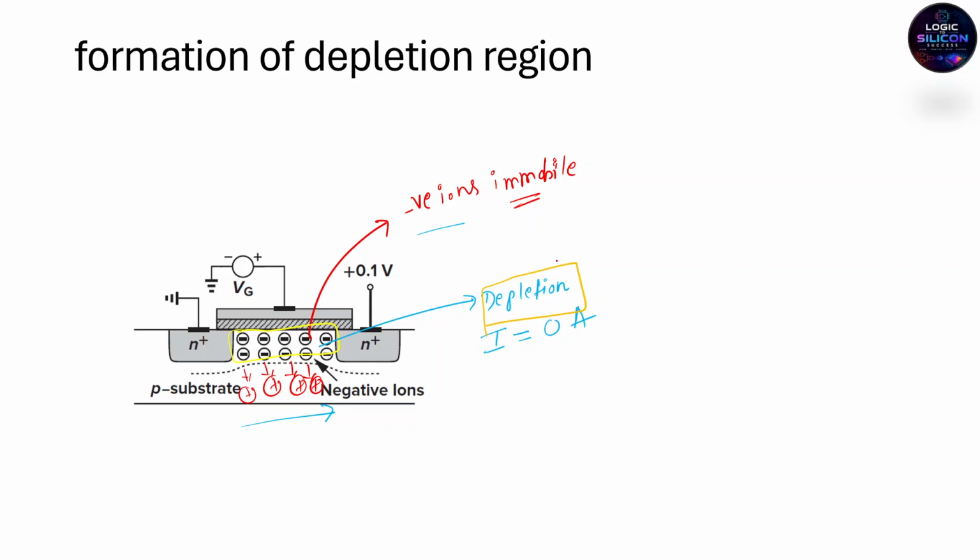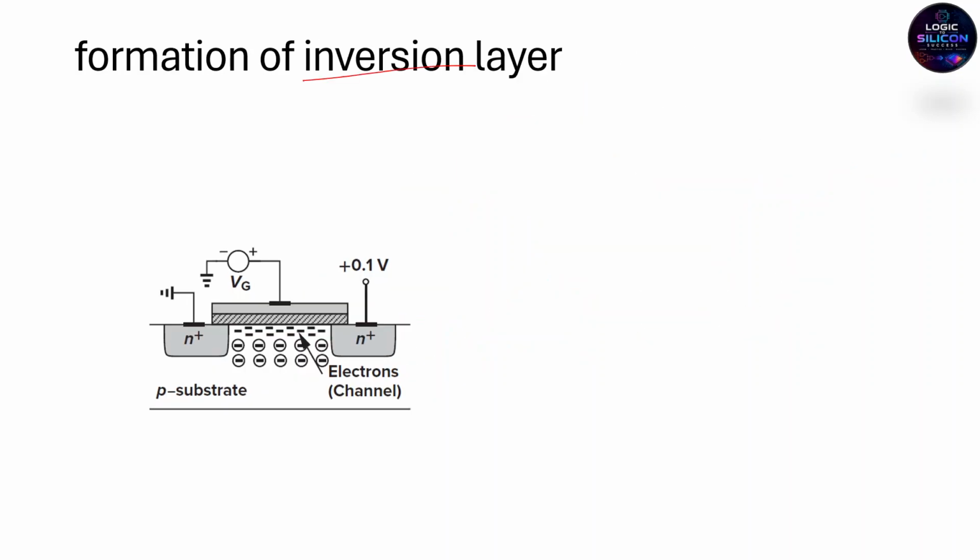So there is a good quantification that we need to do here itself: when Vg increases, the width of the depletion, whatever this yellow drawn layer is, the more positive charge we apply at the gate, the more the width of the depletion region. That is a base concept.